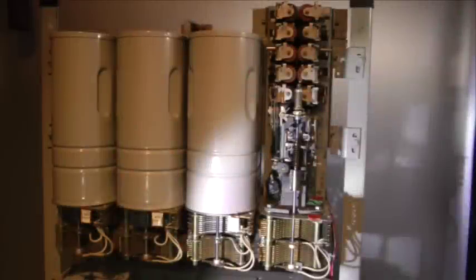The connector is taller than the other switches because it has more relays, and it has more relays because it has more functions to perform. The connector processes the last two digits of the call, these being the tens and units digits of the called station number. In addition to the common step-by-step operations of vertical and rotary stepping, the connector has to perform a line busy test on the called station, ring the called station, trip the ring on call answer, provide answer supervision, and supervise the call connection. Let's take a quick look at a connector in operation.